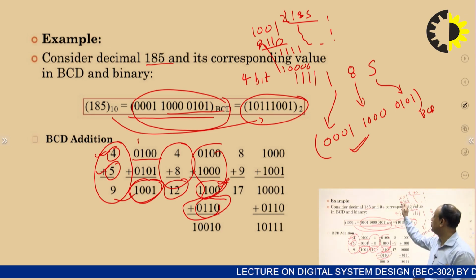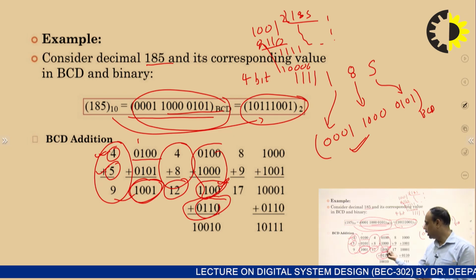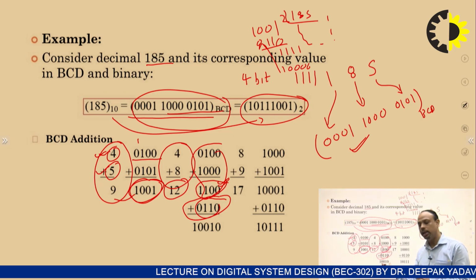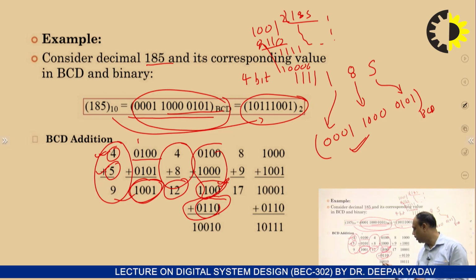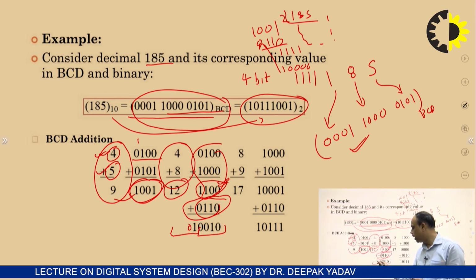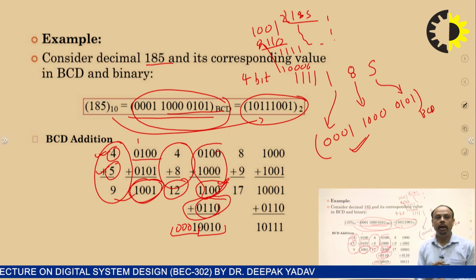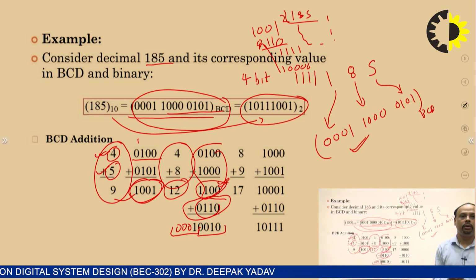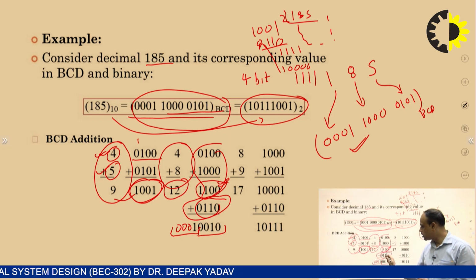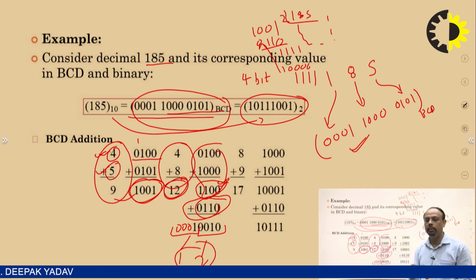As we can see over here, we have to add 6. So the number again comes into the range from 0 to 9 only, this 4-bit number, and one extra bit is added, which again becomes 4-bit equivalent by using extra 0s in front of the extra bit. So this number is converted into 1 and 2, that is equivalent to 12, which is the sum of the two 4-bit numbers.